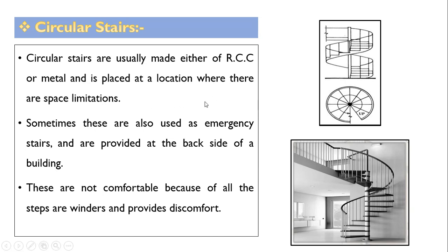This type of staircase is called circular stairs. Sometimes these are also used as emergency stairs and are provided at the back side of a building. Here a vertical central post will be there, and then winders. These are not comfortable because all of the steps are winders and provide discomfort.